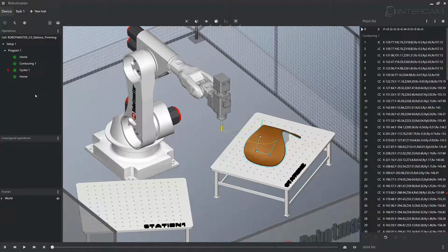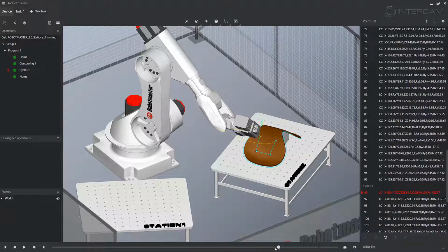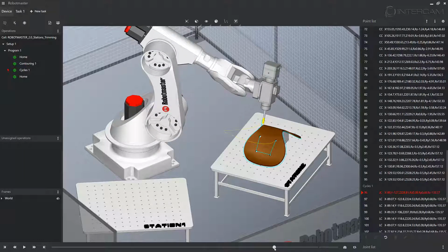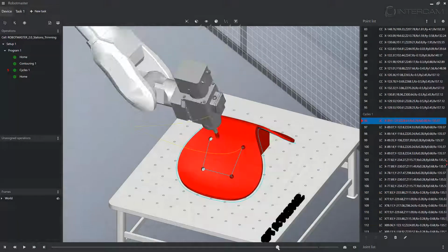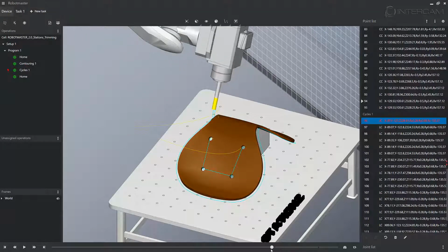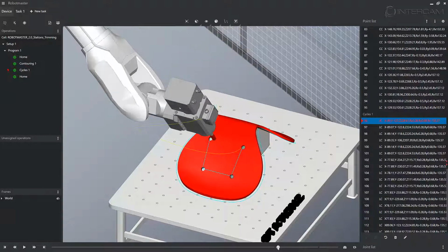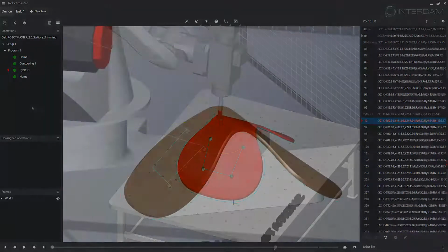Again, there is no need to simulate everything to find any errors. RobotMaster automatically calculates the inverse kinematics and discovers any problems such as collision in the joint move between the 2 operations. You only need to click on the lightning flash to take you to the collision. Joint moves are the bane of robot programmers because they are the principal creators of collisions. This is where RobotMaster version 7 will save you hours of beating your head against the wall.